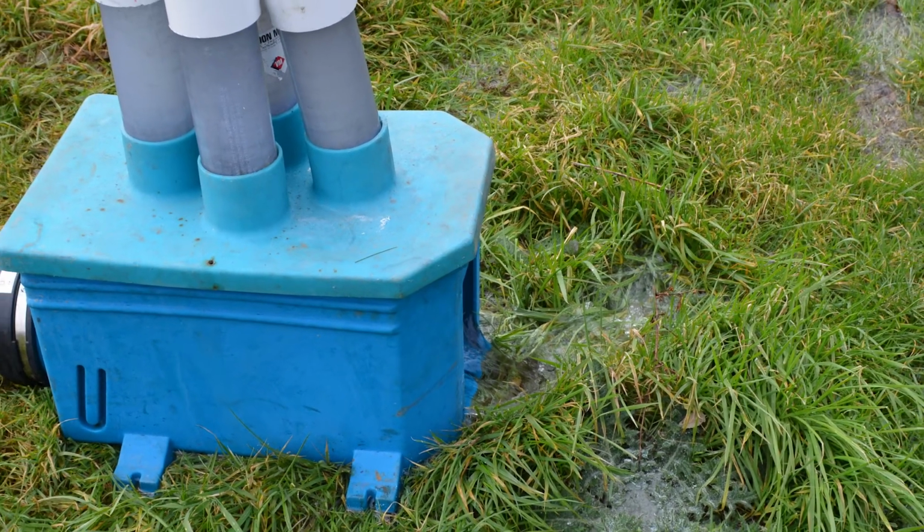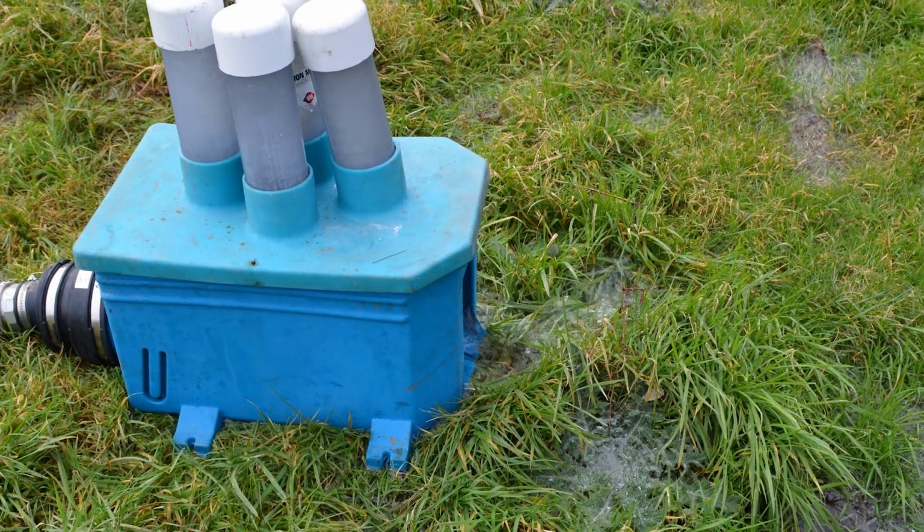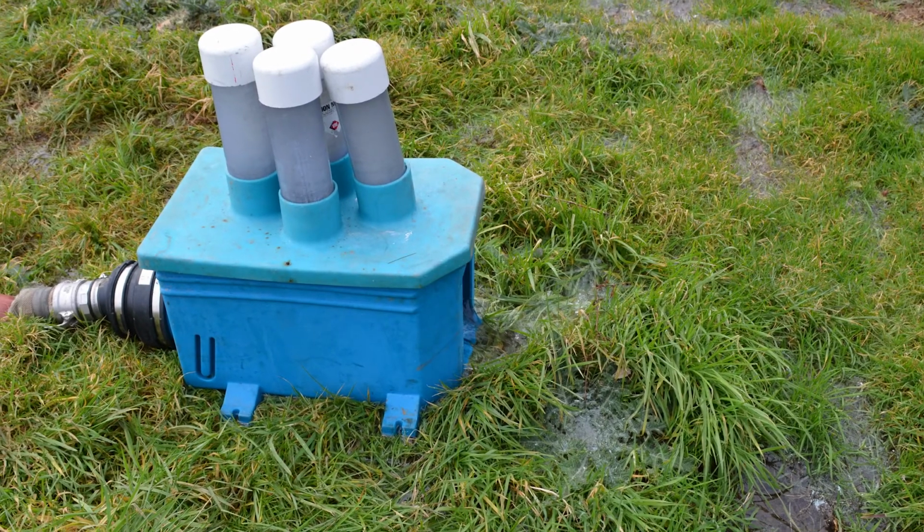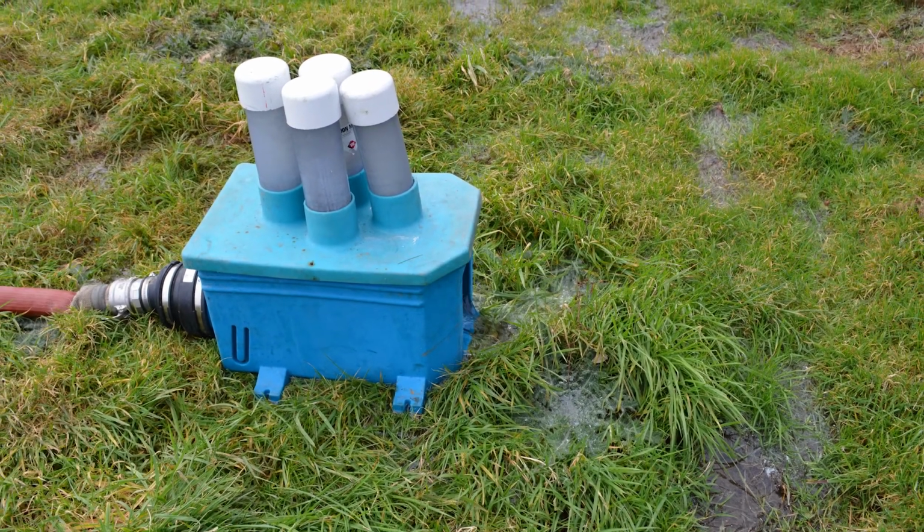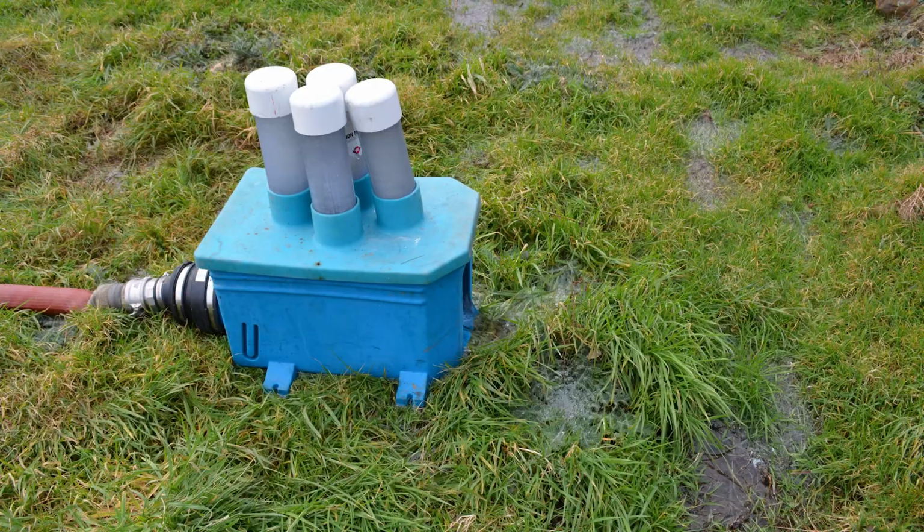We would try and have a container, which is a contact vessel, whereby we put the dechlorination tablet into that, and the scour through a hose would be directed into that container, and the dechlorination tablet would then eliminate the chlorine, dissipate the chlorine in that container, so that when it leaves the holding container, we have chlorine-free water, which won't do the aquatic life any harm.